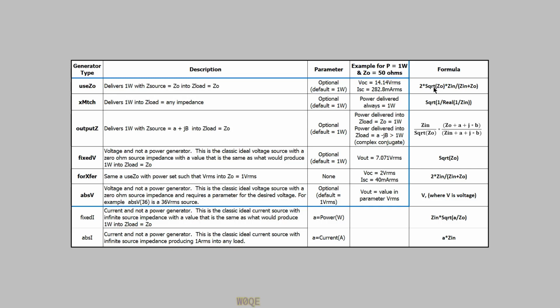And I know this one can be done a couple different ways for sure. This one was a little trickier to do, but they're fairly simple. What you do is you write a couple formulas, and what you are trying to define is the voltage at the interface from the generator to the load based on all the things you know about. Zn is the impedance looking at that interface to the left.